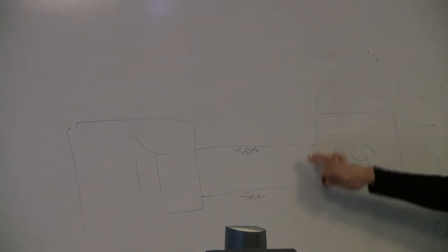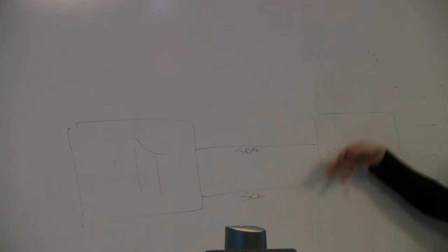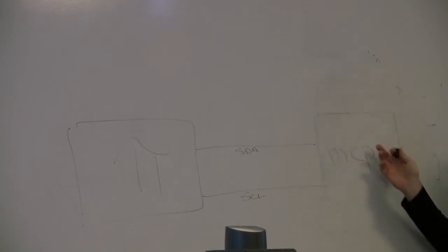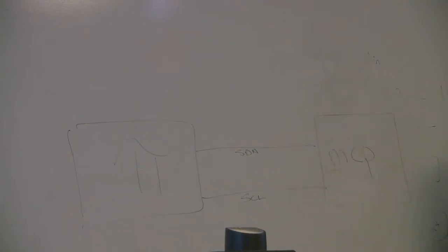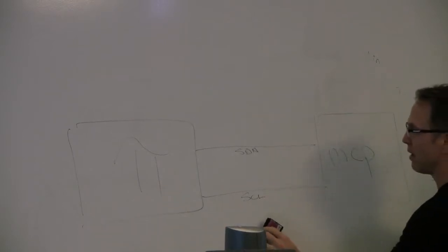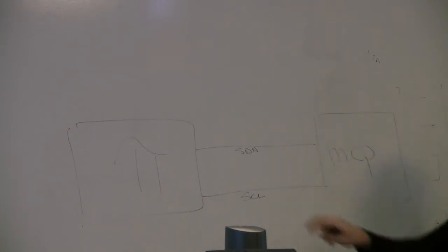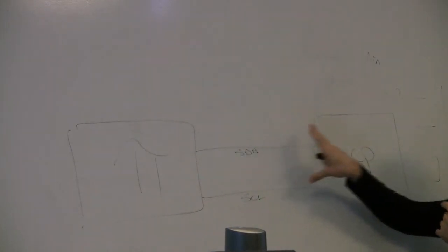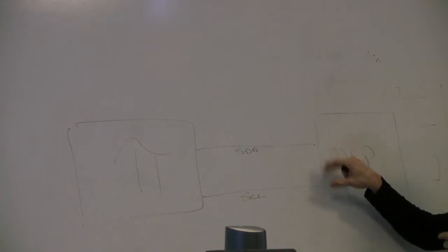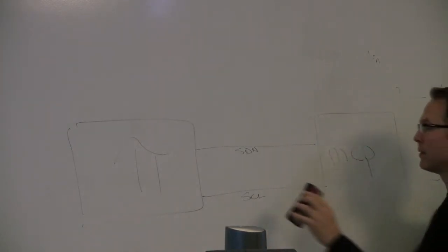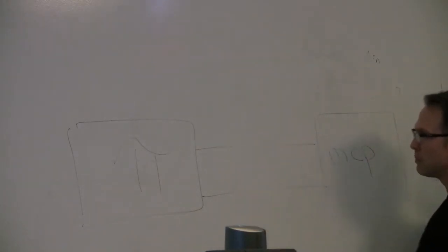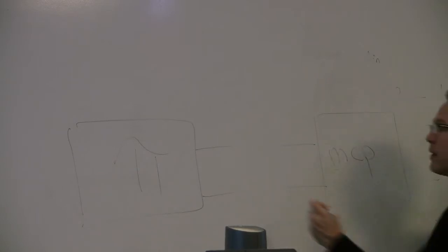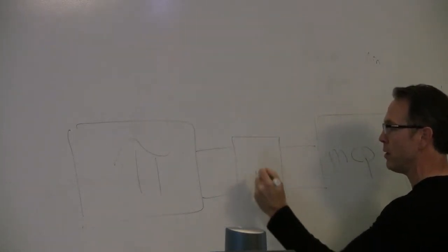Correct. On these lines, I2C needs to be pulled high. So first question, which side do you want to pull high? It isn't convenient to disable the pull-ups on the Pi side, so the quick answer is that it's being pulled up by the Pi. So then they'll be pulled high to 3.3, and the question Paul raised is, will the MCP recognize those as being pulled high when they're only at 3.3 volts? I'm already using it at 3.3, so I already know that it works at 3.3. Carl's saying they might be close enough. But the other way to do it would be to put the level shifter in between, right?